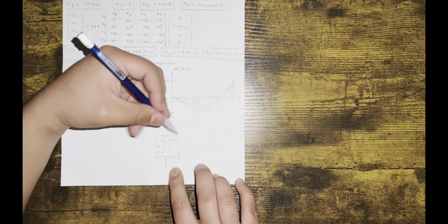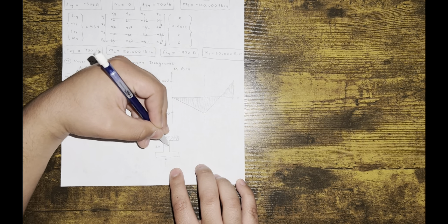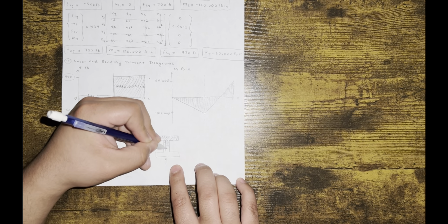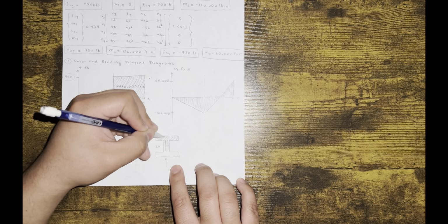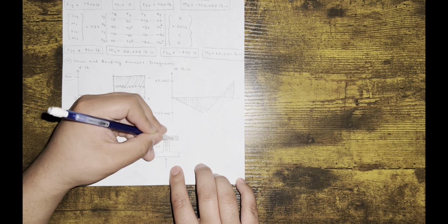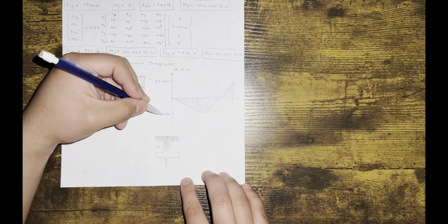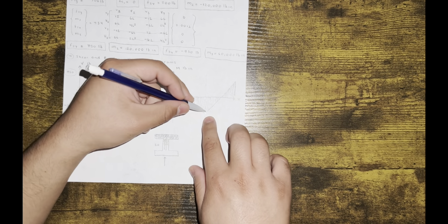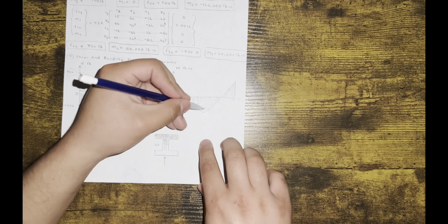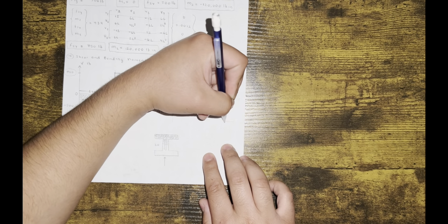So you need to make sure this section, and this section too, technically, right? But sometimes in industry, these things are very thin wall, so this really is your bending material. So you need to make sure this section up top can withstand 120,000 pounds of moment, at least at this location, right? This could be a whole beam, and it doesn't have to be continuous, right? The beam could be very beefy at this location, so we could have this.